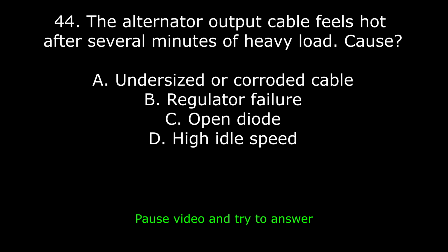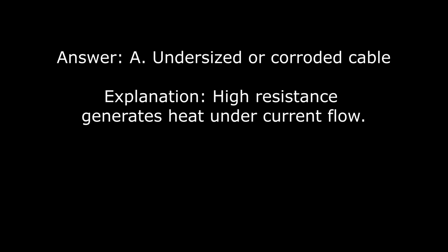44. The alternator output cable feels hot after several minutes of heavy load. Cause: A. Undersized or corroded cable. B. Regulator failure. C. Open diode. D. High idle speed. Answer: A. Undersized or corroded cable. Explanation: high resistance generates heat under current flow.